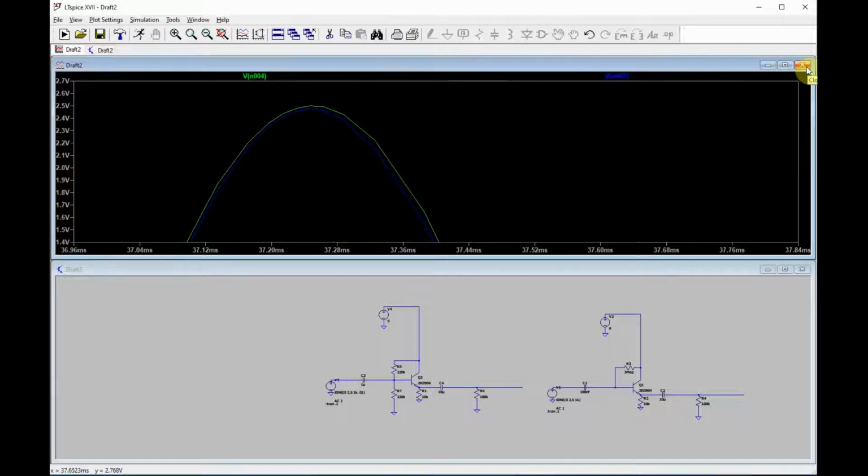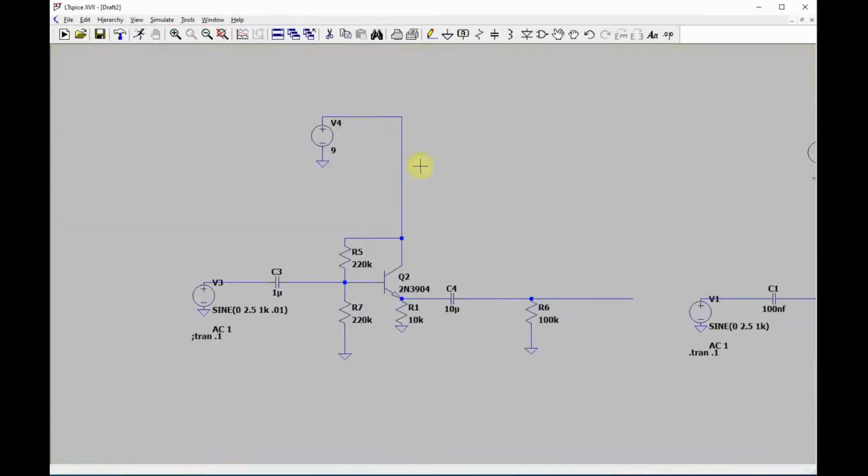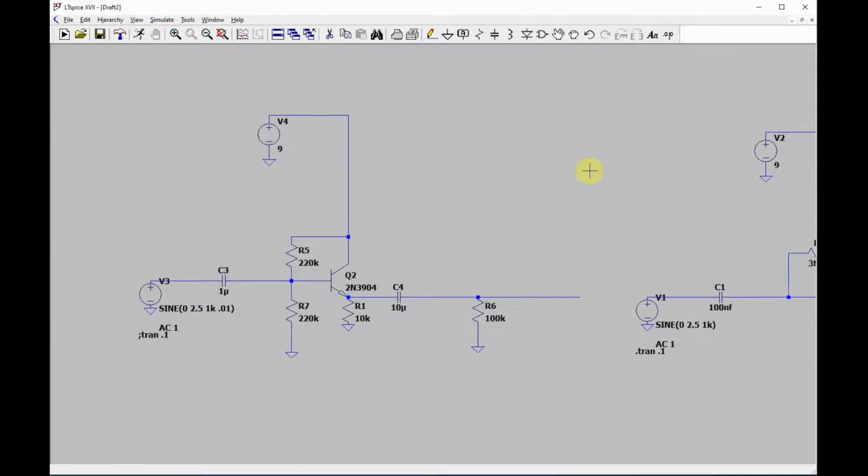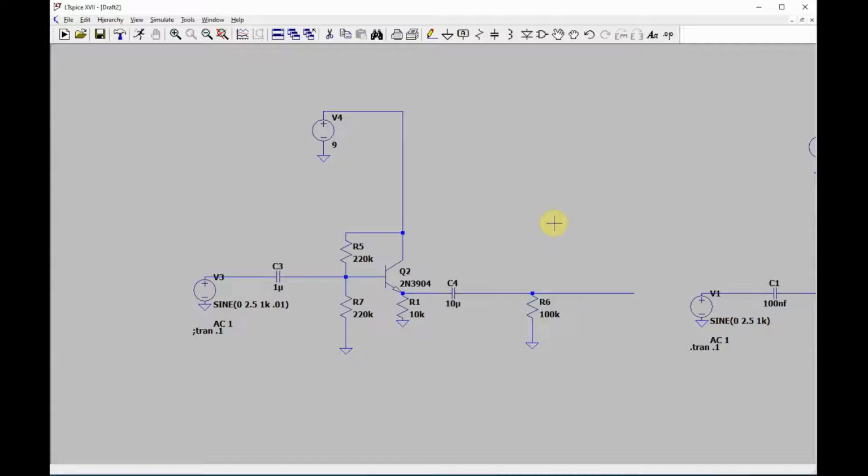And why a buffer in the first place? I guess we haven't talked about that. But the point of a buffer is the signal sees a high impedance, or high enough impedance. It copies it. It puts out the same signal, but this same signal has a lower impedance. See, every time you go from one stage to another, you're supposed to multiply by 10 in terms of the impedance. Anyways, that's what the buffers are used for.